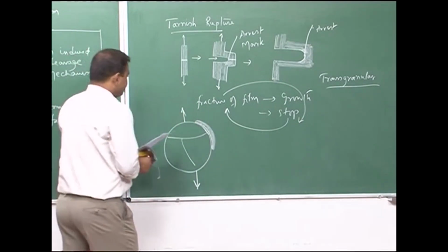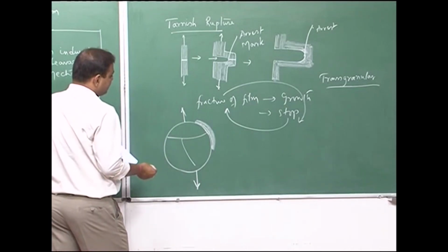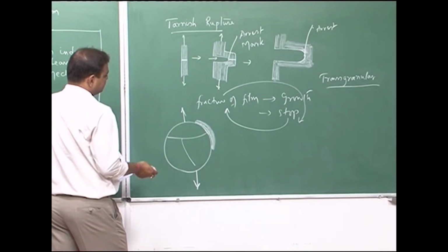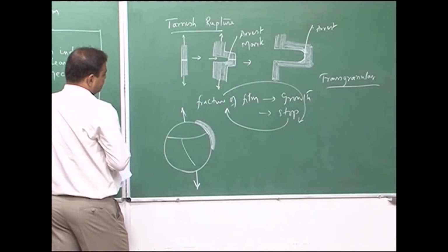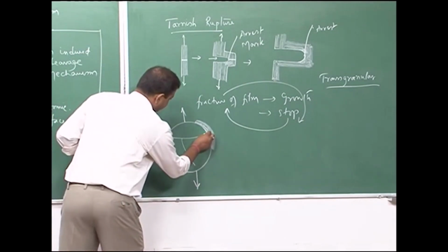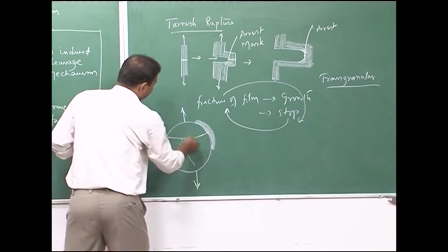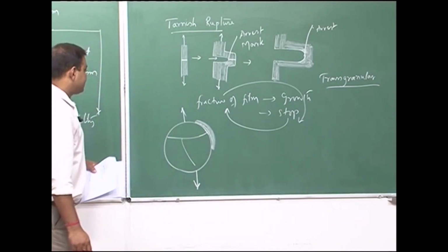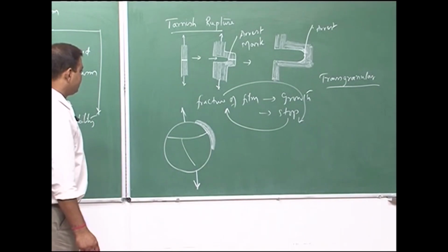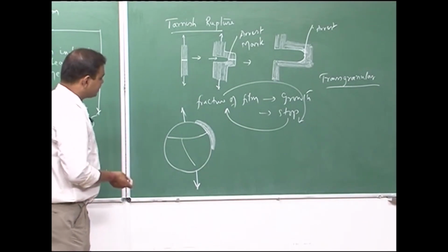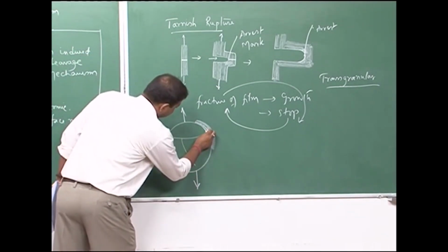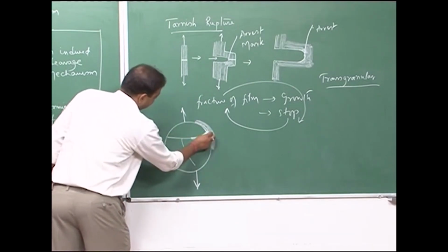Now, at this grain boundary, the tarnishing action, or the oxidation or film formation, because the grain boundary zone is a highly diffusive zone because of selective precipitation or selective segregation along the grain boundary, this zone will get tarnishing.